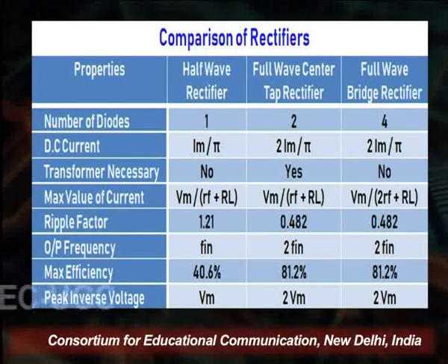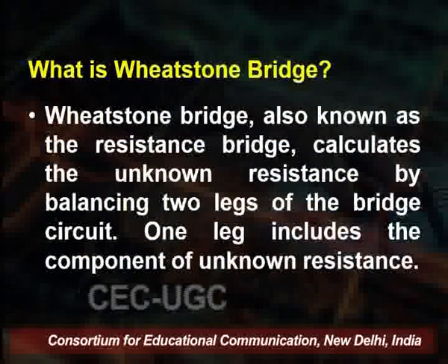Maximum efficiency is higher in the full wave center tap rectifier and the full wave bridge rectifier as compared to the half wave rectifier. Peak inverse voltage will be more in both the full wave rectifiers. So this is the comparison chart.